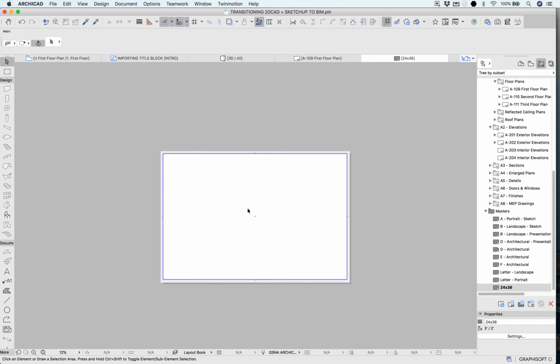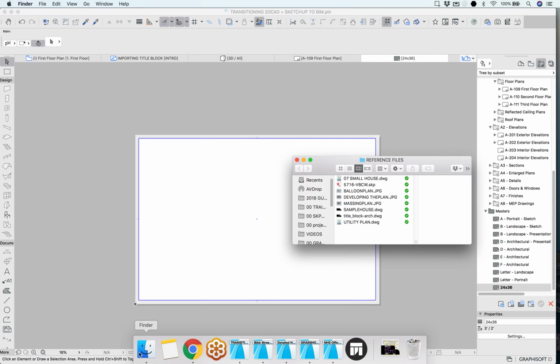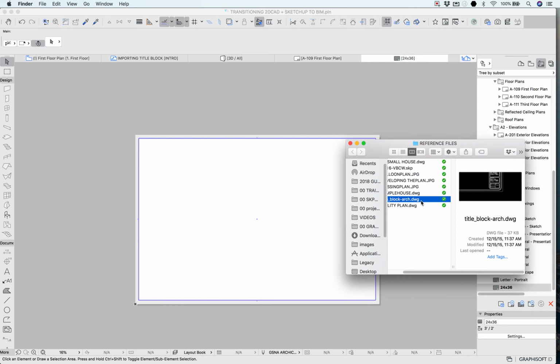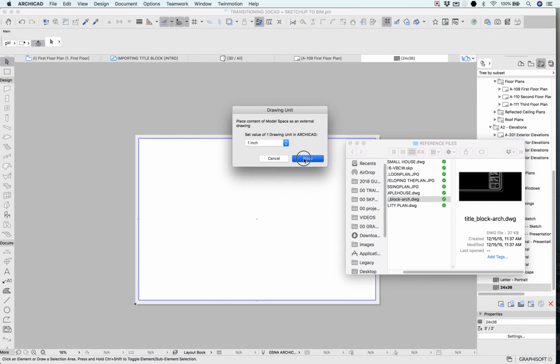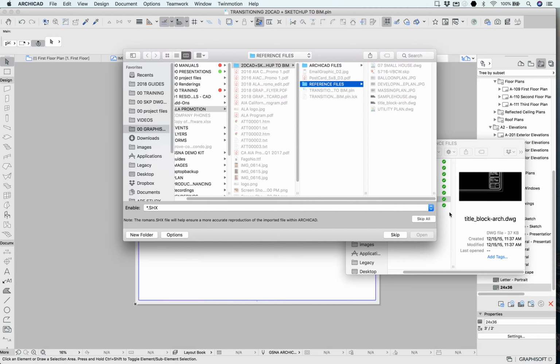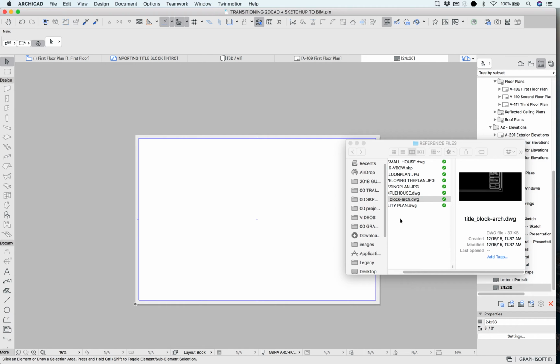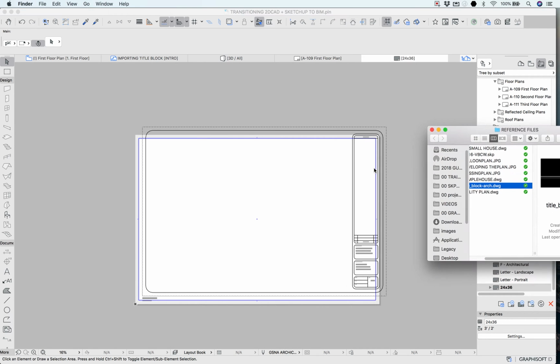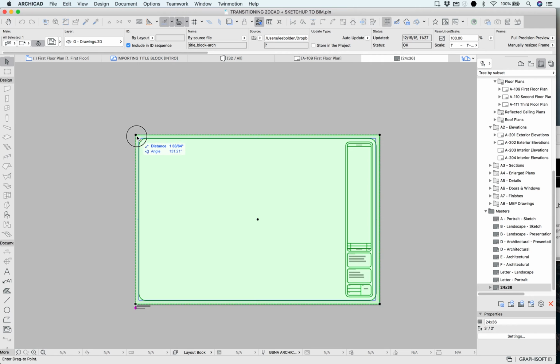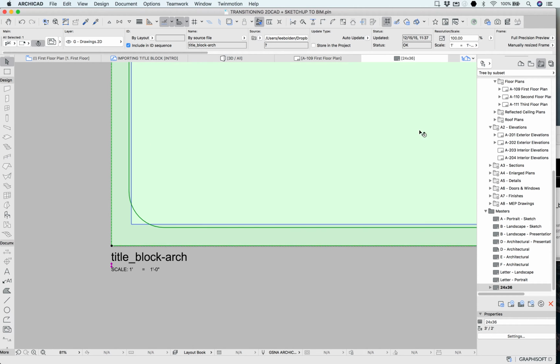So when we create this, all it takes, if you're getting started here, you want to start to see how this develops in terms of your plan. Bring in your title block, and you can do that simply by dragging and dropping it. And when you do that, it's going to ask me about scale. Usually 1 inch is great, but we're going to place this element. These are files that you can attach to it that can offer you more control over fonts and values here, but we're going to bring this title block in, and we'll talk a little bit about this when we get back in terms of what it means to bring in drawings.